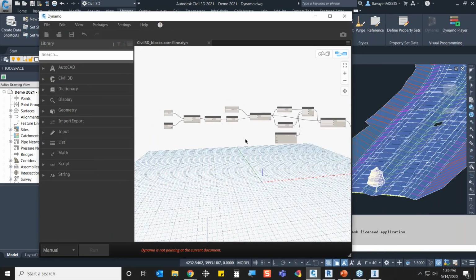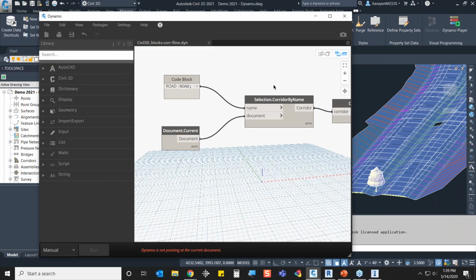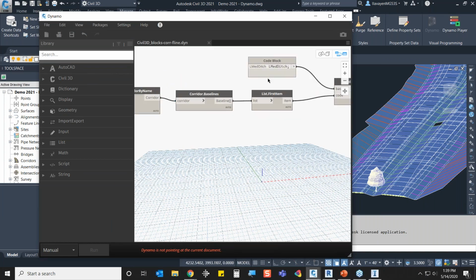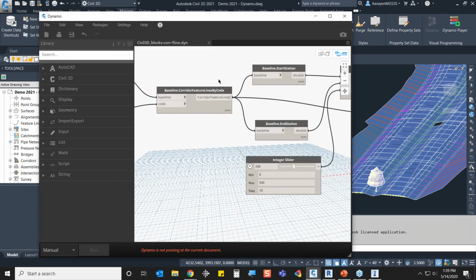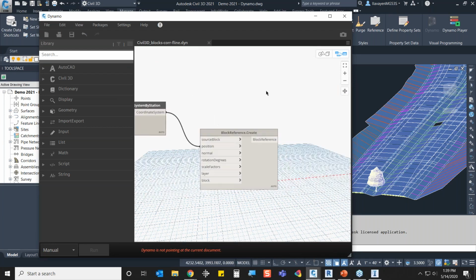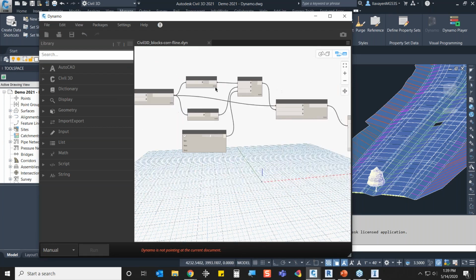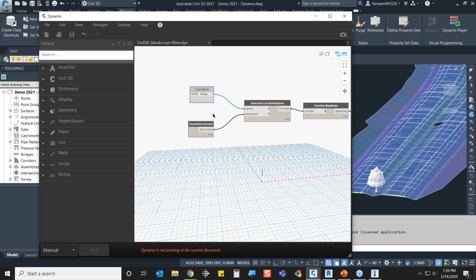And this is one of the routines that it has. I mean, it's crazy programming inside of here. It tells it what to do, what not to do, how to behave. It is scripting out automation. So most of that manual work, that repetitive work that you're going to have to do, creating driveways at a certain iteration, bringing in trees, bringing up pavement markings, bringing in blocks. If there is a script that you're following, we can have that happen within Dynamo.